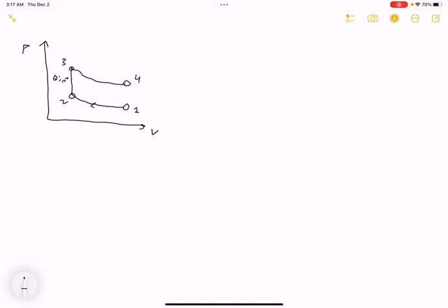Now, of course, when we decreased our specific volume in the compression process, the pressure went up. And when we increase it, the pressure is going down. So that's curving down and to the right. And then, of course, we have the heat rejection, which also occurs isochorically. So in a real engine, this is like the exhaust.